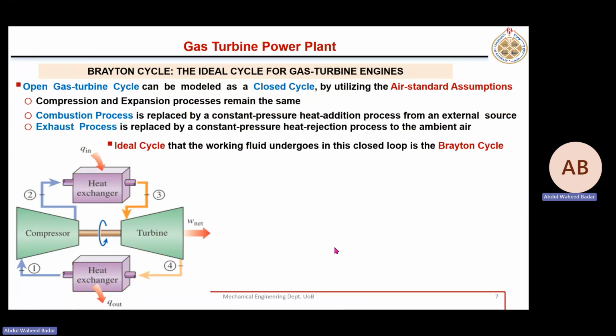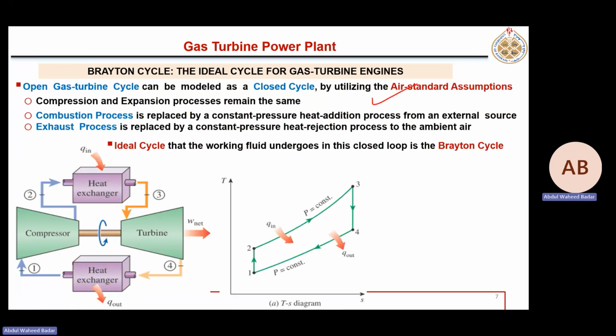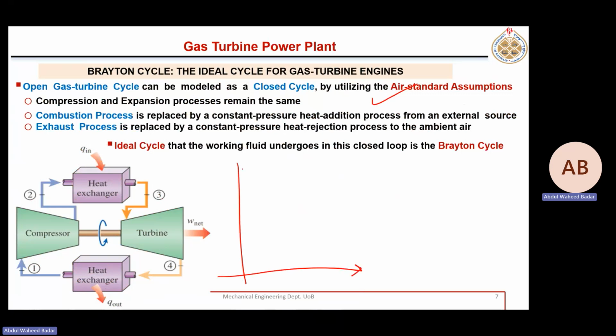So this is what we already covered in Thermo 2 also. So we can go through it now. TS diagram. Okay, let's draw the TS diagram. Now in this chapter, no need to show the dome because we are entirely in the gaseous region. So starting from compression, 1 to 2, isentropic compression, then 2 to 3, constant pressure heat addition.